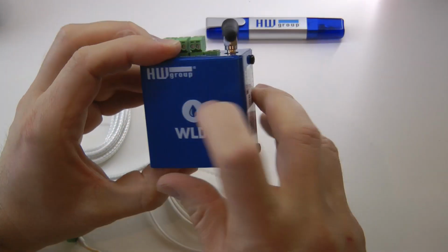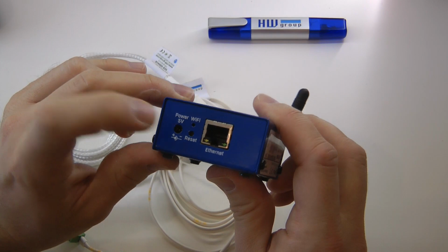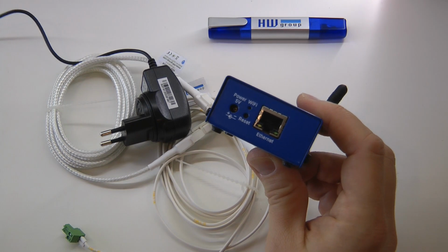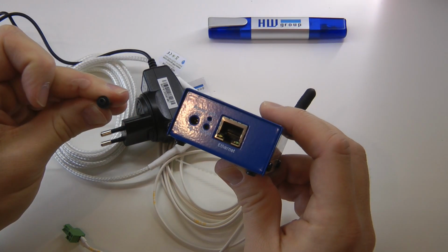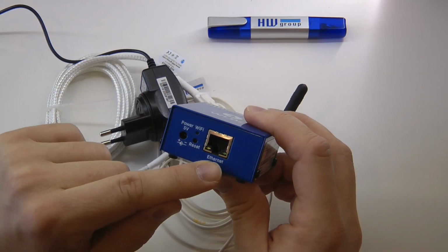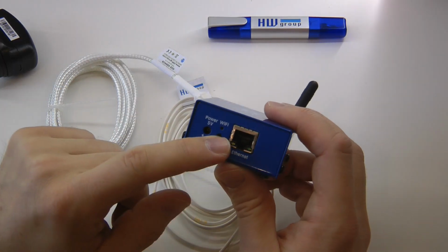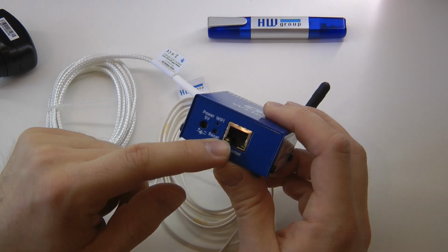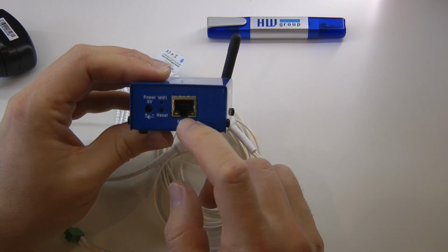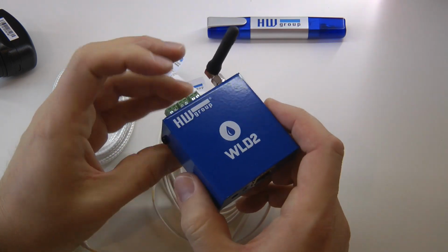As you can see, it comes in a metal box, and on the front we have a couple of power and network connections. So you can power this device from the 5-volt supply, and for this there is a 5-volt power supply which terminates in a barrel jack that's provided in the kit. In terms of the network connection, there is an Ethernet connection, so you can wire it to your existing network. But if you prefer, it is also possible to set up a Wi-Fi connection. And if your network has Power over Ethernet functionality, you can actually use the Ethernet cable to power the device. So in that case, you don't need an external power supply.